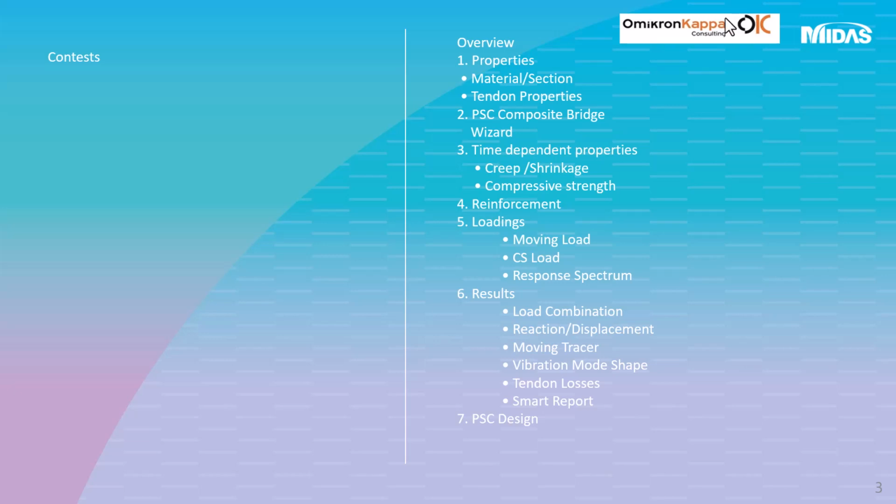Then we are going to define the time-dependent properties in order to find the creep and the shrinkage for the construction stages, also the compressive strength. Then we'll see how we apply reinforcement on the cross-section of the deck.